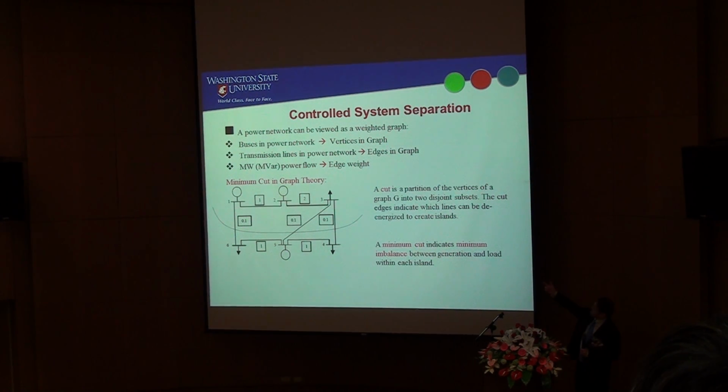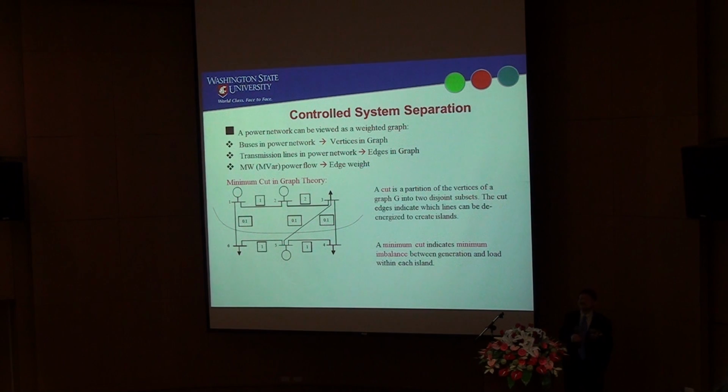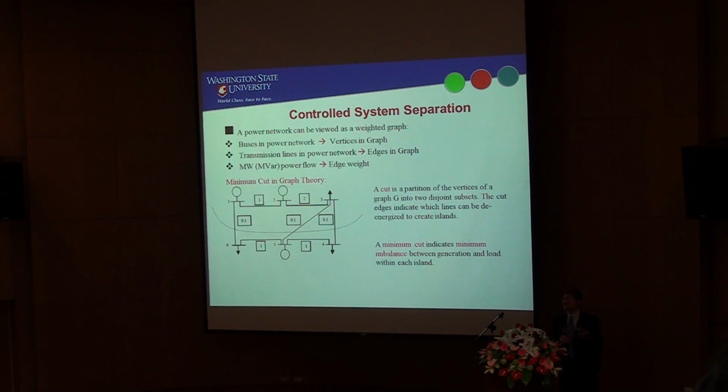But before I can talk about that, I will say a few words about the reconfiguration of power grid, which is one of the so-called defense actions. If the system is really in trouble and you don't have better alternatives, one way is to split the system. When you split the system, hopefully the major part of the system will survive, and the disaster will not propagate too far to the entire grid. So that's why this is one of the self-healing actions that people have been studying.